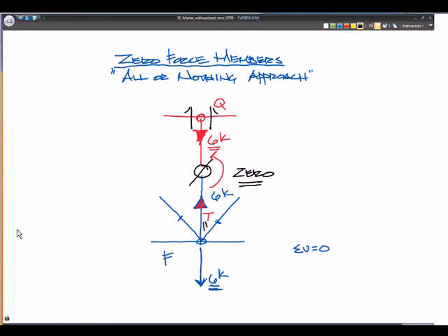Because even if we said 1 kip went in there, it still would be no good at the other end. So all of this force has to go into the diagonals. So that's how we can determine very quickly if FQ is a 0 force member. Can you do anything with it at the other end?